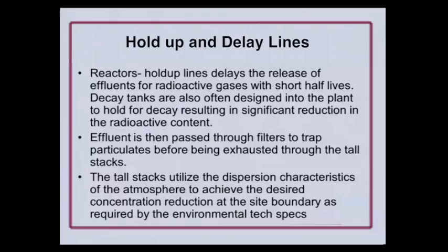What they do is they add piping. That's the delay lines they're talking about. And then it would be fed into the plant exhaust stack, where whatever is remaining would be discharged out with the regular air exhaust. Now this all has rad monitoring on it, as we talked about earlier as far as discharge.